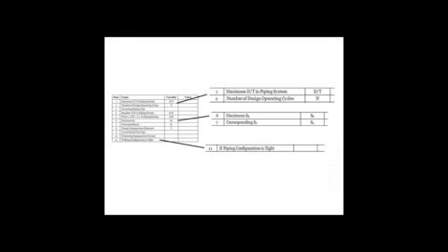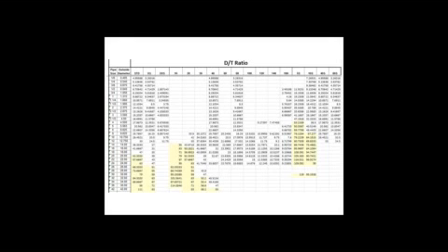What we're going to see with some of the examples that we look at is that piping systems can be huge, but there can be local areas in the piping system where they're tight, highly stressed, and with large D over T's, and that's what we want to attack. Here's the D over T ratio chart. What you see in light yellow here is where we have D over T factors that are greater than 50. So there's not very many. Most of what you do just doesn't need to be looked at in any greater detail.